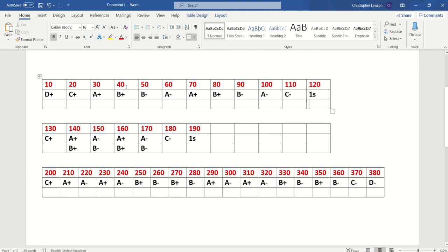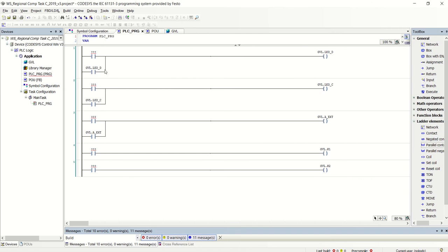So as I said, all the hard work's done. It's telling us when we should be activating each output. So if we just look at D should just come on in step 10. D isn't referenced anywhere else there. So how do we get that to trigger? Well, we've got to do some of our comparator commands.